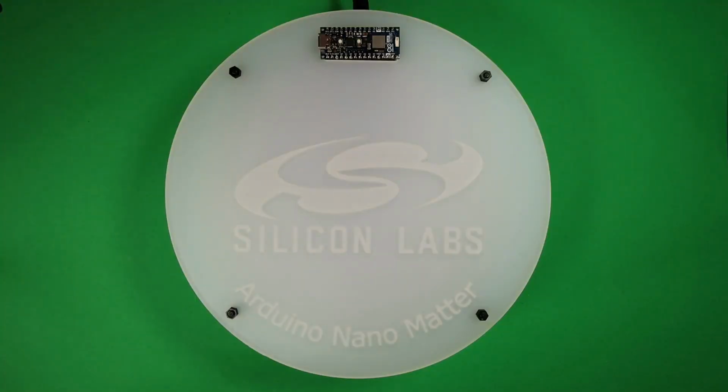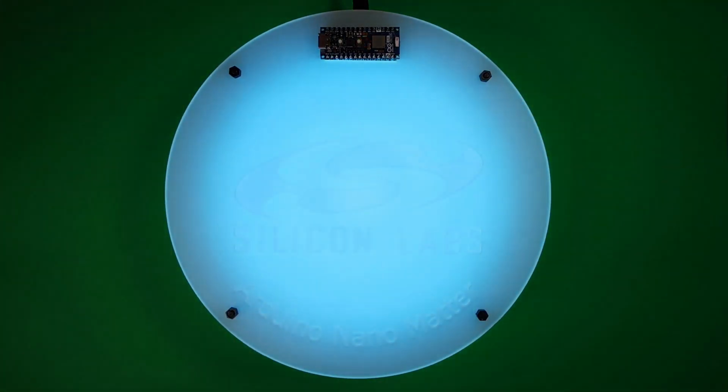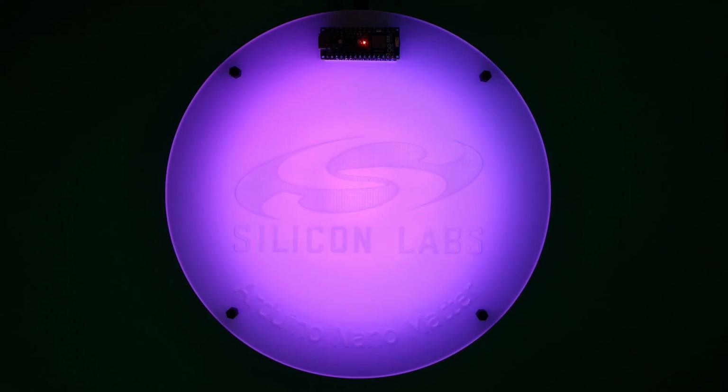After the firmware is flashed, the board reboots. This time it will skip the commissioning stage, so we won't see the LEDs going to the dim magenta colour. Instead, we will see dim yellow as it reconnects, followed by dim cyan as it waits to be queried by the hub. The time taken to come online will depend on your hub and may be a few minutes.